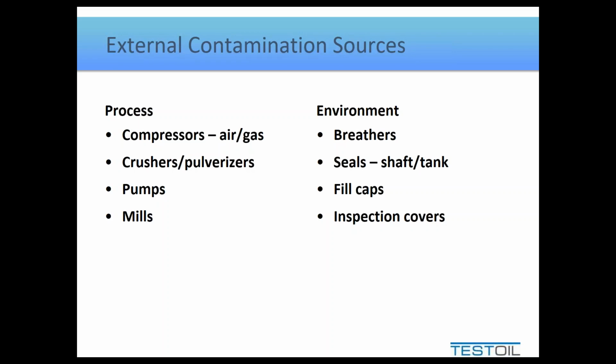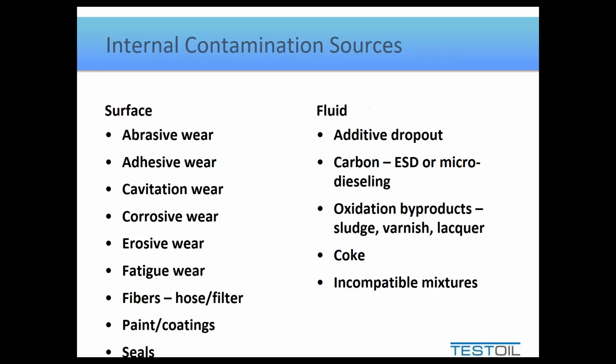And it's simply that they may not be sealed correctly, they may not be adequate, they may have damage to them. Many times we've seen spikes in particle counts on systems that have been running fine for years, and all it turns out is somebody didn't replace a dipstick or didn't put a fill cap on properly, or perhaps even a breather was damaged.